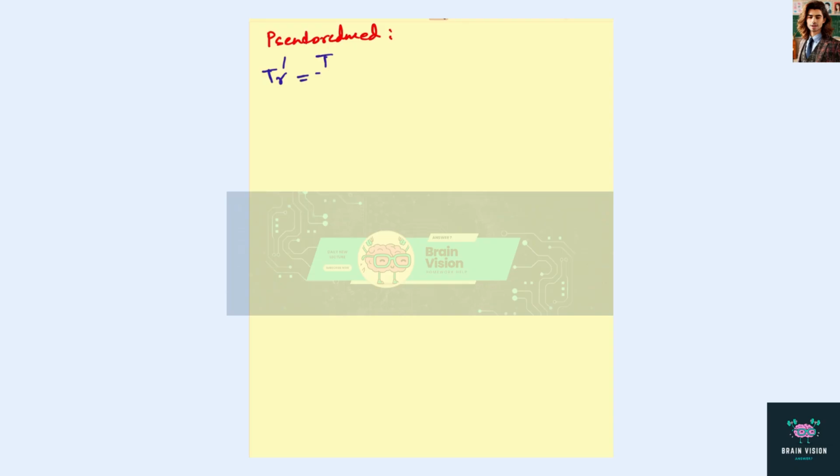Next we need to calculate the pseudo-reduced temperature and pressure. The pseudo-reduced temperature is the temperature of the system divided by the pseudo-critical temperature. The temperature of the system is 363 Kelvin, and the pseudo-critical temperature is 274.8 Kelvin. Therefore the pseudo-reduced temperature is 1.32.